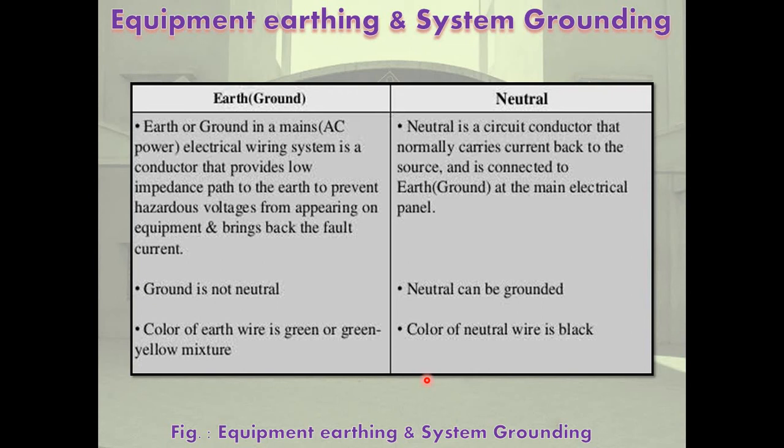In ungrounded systems, during a single earth fault anywhere in the system, the voltage of the two healthy phases with respect to ground rises to √3 times the normal phase to ground voltage. Such sustained overvoltage is harmful to motor insulation. Hence, the ungrounded neutral system is no longer preferred for supply systems. All modern systems are with grounded neutral.